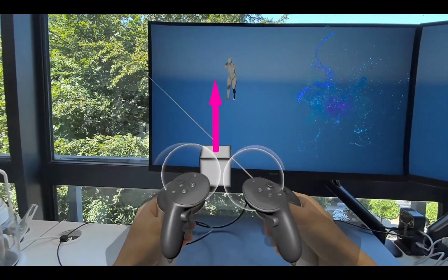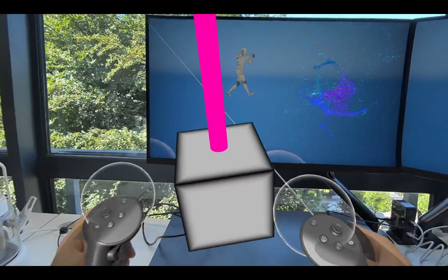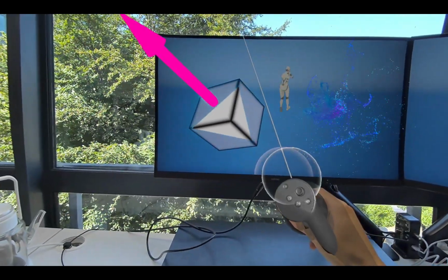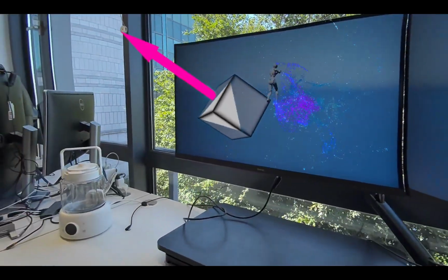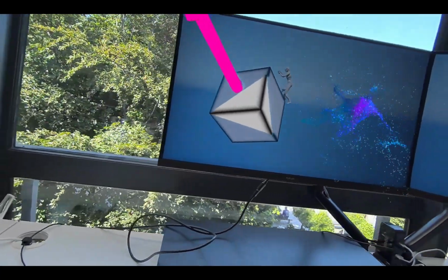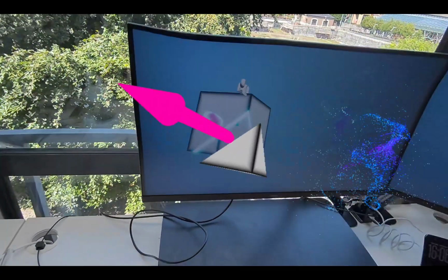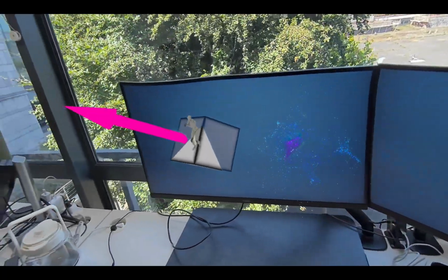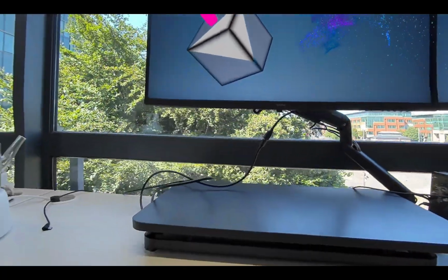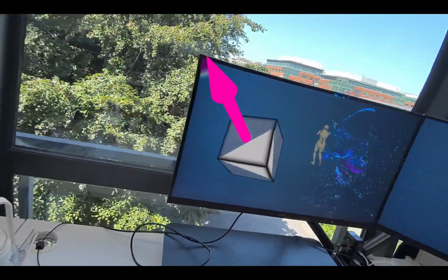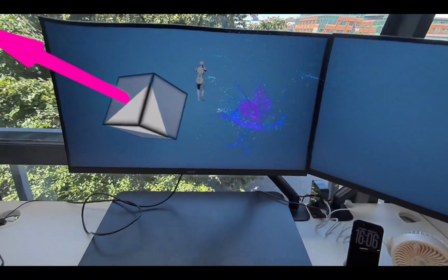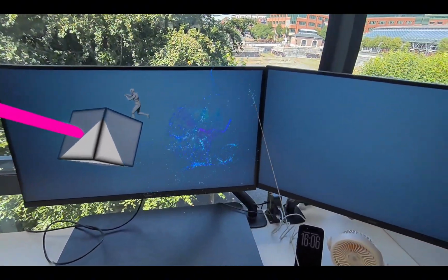For an installation where the dimensions and spatial relationships of the screens can be measured accurately, you can enter the measured screen sizes and transforms directly into the PC nDisplay configuration. During HMD calibration, you can then disable Should Control PC Screen for every screen. In this case, you only need to align the size and pose of the primary screen calibrator.